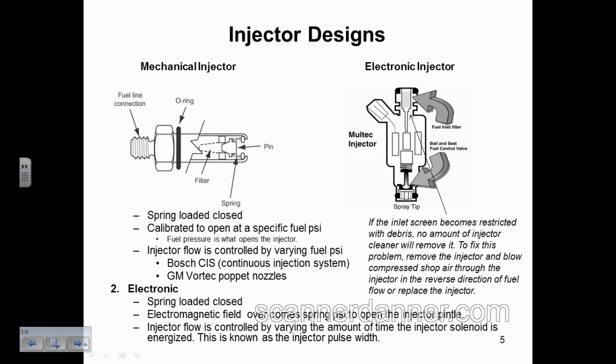Okay, page 5, as far as the injector design, I think the main purpose for me for this page is really to talk about the hybrid GM CPI system. And you guys know that as the Vortex system. The 4.3 that they used in the Blazers and the S10 pickups forever, from maybe 92 or 93. They also used a design for this in the V8 Chevy trucks. And even when they went OBD2, they changed the CPI system to a sequential CPI system. So that's again, my main purpose is to really talk about that hybrid system.